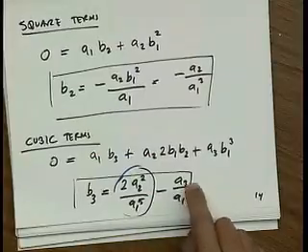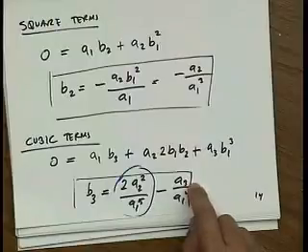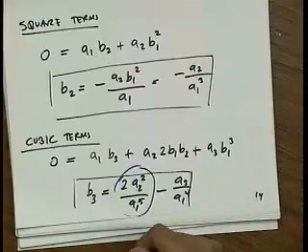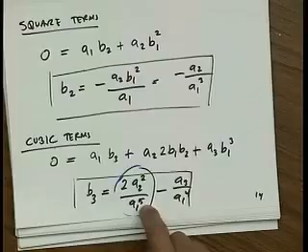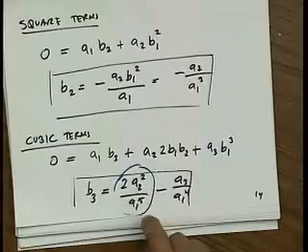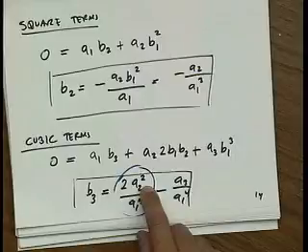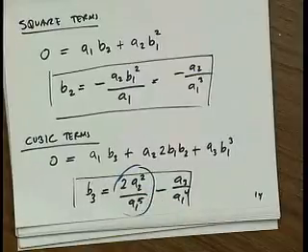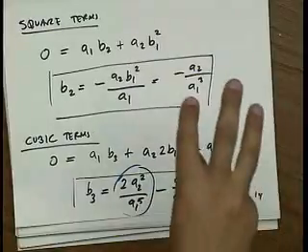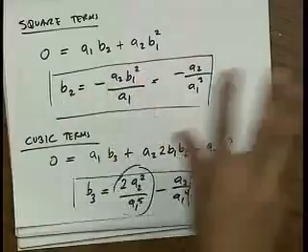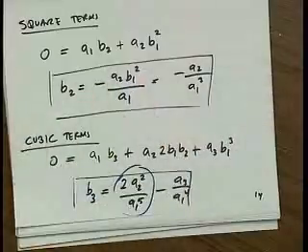That means that in the inverse relationship there is no cubic term. When I invert that equation, though, I can have a cubic term. So A2 interacts with A1 and produces a cubic term in the inverse. So just because the amplifier output to input relationship doesn't have cubic, doesn't mean that the inverse does not.